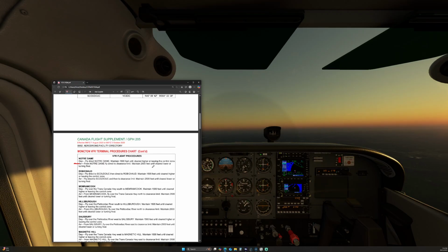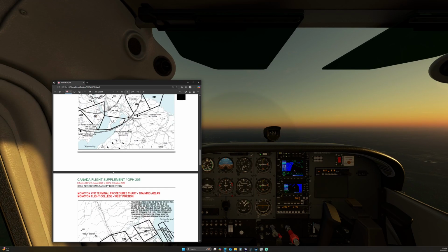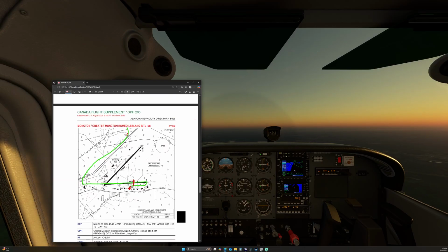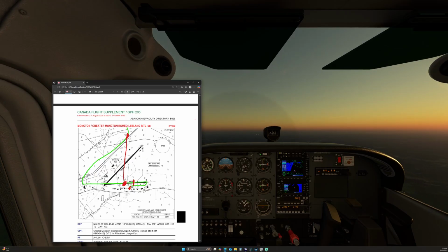Once we're there, we'll descend about 1,500 feet over the airport and join the left downwind. We'll come in just about here, about midfield, at about 1,700 to 1,800 feet. And we'll descend down to circuit pattern altitude in the downwind. We'll make a left base for 29, and we'll plan to exit on Bravo and then taxi back in.